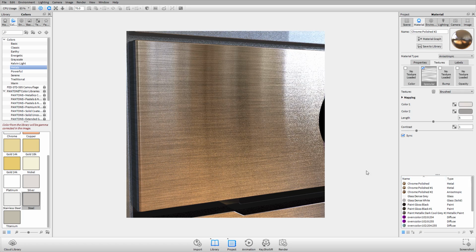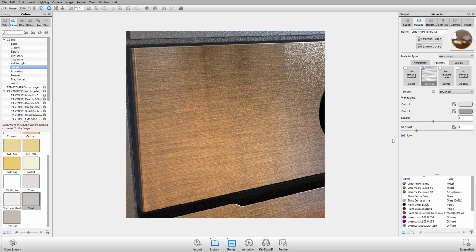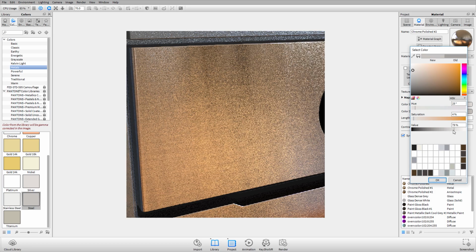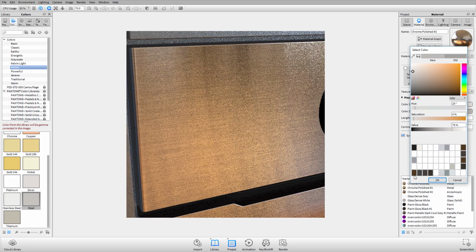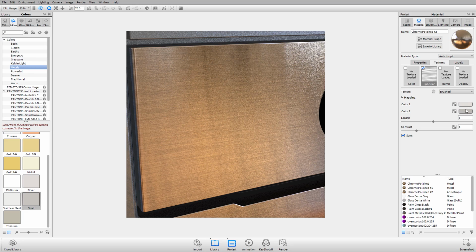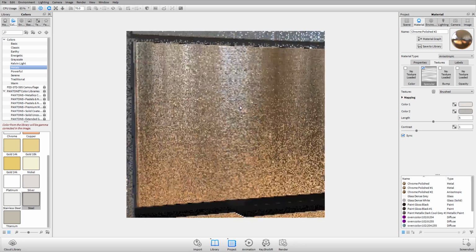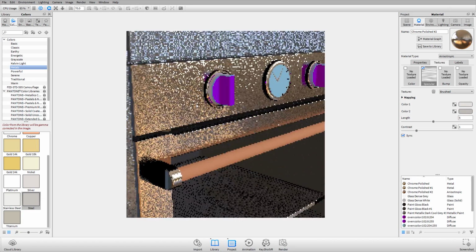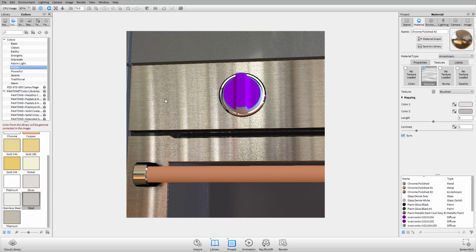So we're controlling the reflectivity of our material using two colors. The more contrast you have in the colors, the more contrast you see in the grain. So if I want to make that a little bit finer grain, then I can make those closer in value. So let's say 75. So the average color is like 85% because we have 95 and 75. So the average is 85. We have an 85% reflective material. And now you can see vertical highlights, horizontal grain, and we're using that brush texture. That's pretty much how we can build our more advanced brush finishes.